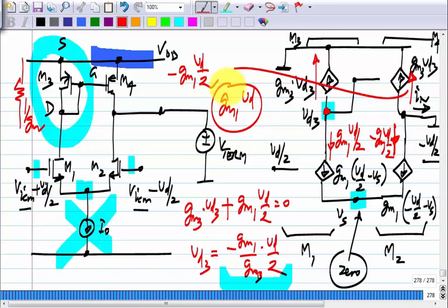So, actually the equivalent is very simple, the Norton equivalent current. What is GM1 times Vd? It is again like a common source amplifier. If you had a single transistor of transconductance GM1 and you applied an incremental gate source voltage equal to Vd, the incremental drain current would be GM1 times Vd. That is why I keep saying a differential pair is just a fancy common source amplifier, except that you can apply inputs differentially, and the inputs will be treated symmetrically and so on, otherwise it is the same. Now, we can also reason it out from here.